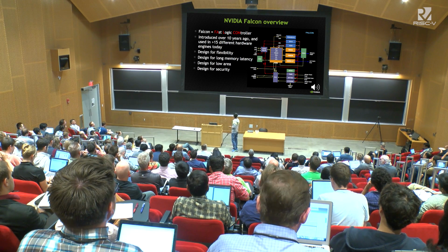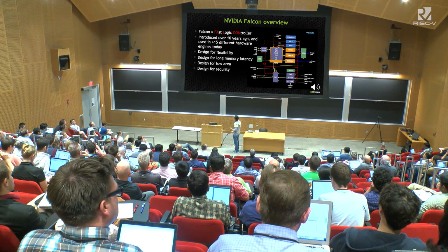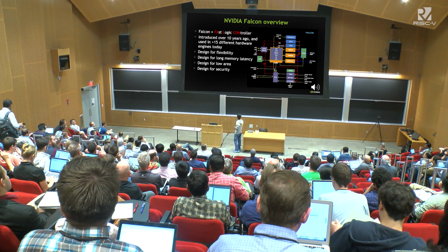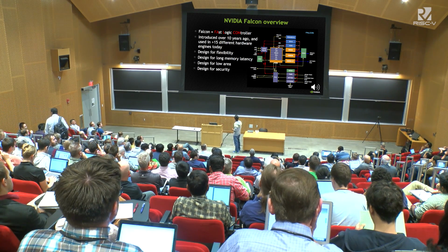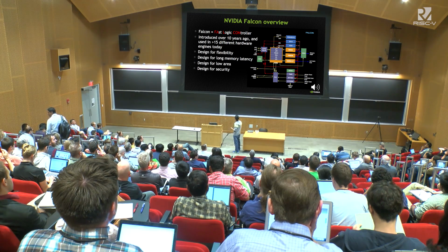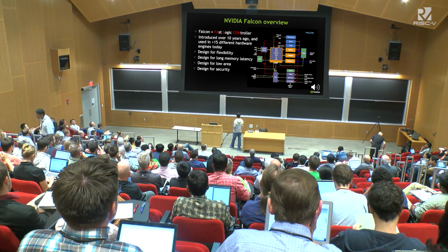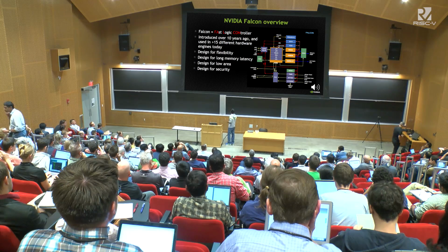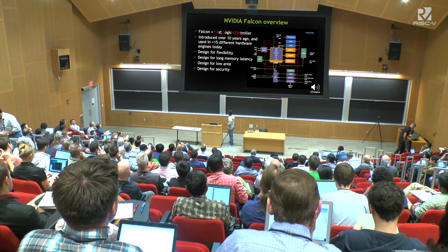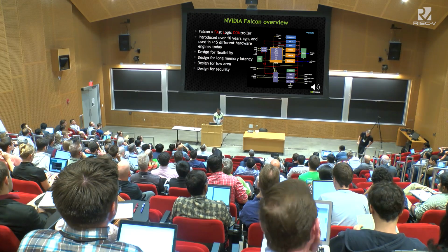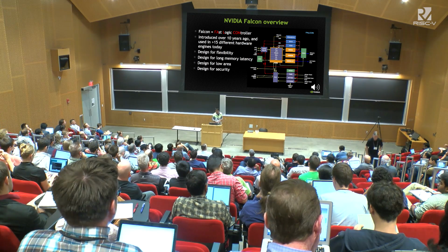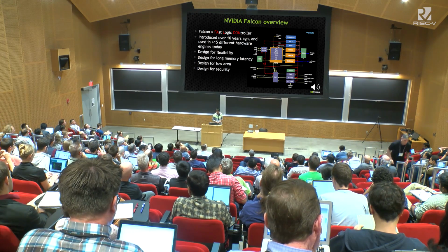If you are familiar with GPU architecture, there is a host that sends methods down to the hardware engines, for example, video engines and graphics engines. The command streams are usually hard for the hardware engine to interpret. So we need a lightweight, programmable CPU to help process those methods and program the hardware. And that's why we invented this Falcon CPU.